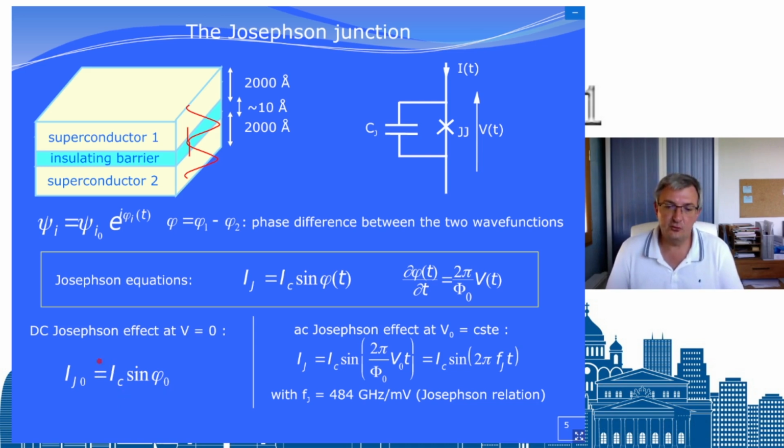So you need to maximize I_J naught, so you want the sinus to have the value of 1. The best way to do that is, first, to pass no current at all when you cool down. The device should have no current through its terminals. The second is to cool down in a very controlled way, very slowly, to make sure you get the best configuration.